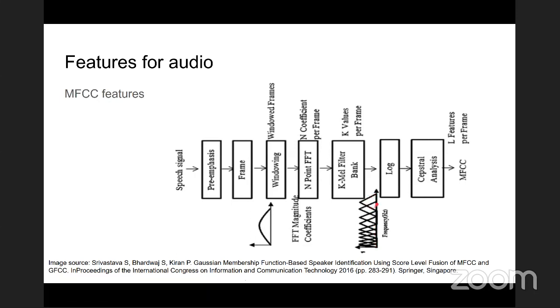And these summarizations are actually based on overlapping bands, and the overlapping is in some triangular fashion. So it's based on people who had studied audio signals very deeply. Then you take the log of that, because loudness in decibels is on a log scale, and based on that you get the MFCC coefficients, and you use those in your classifier. So these MFCC coefficients become your x1, x2, x3, etc.